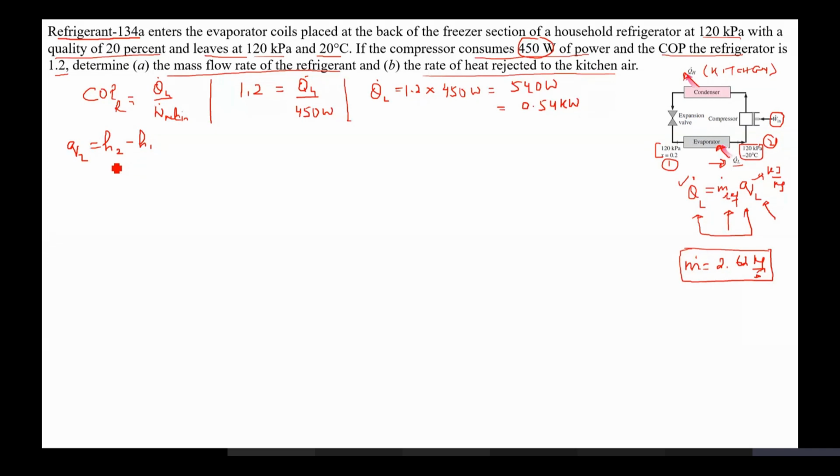No, it is not W dot plus Q dot. It is the difference of the enthalpies at the two states that would give you the heat transfer through the system. If you apply the energy balance on this evaporator as a component, E in equals E out.